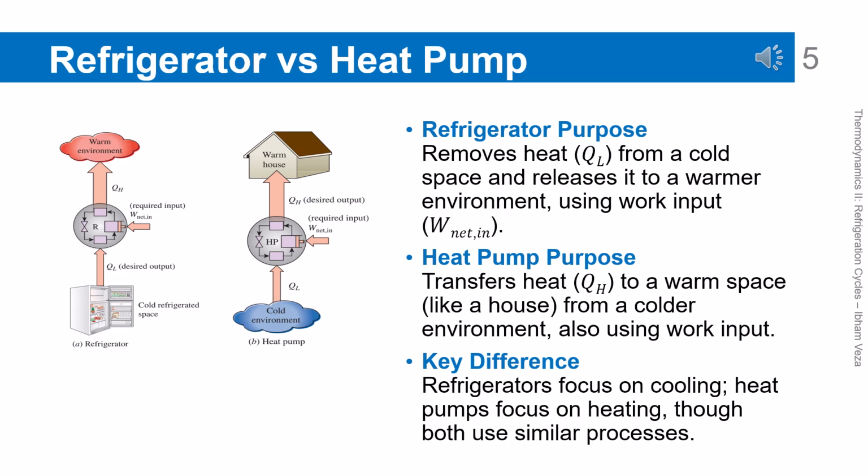Refrigerator versus heat pump. A refrigerator is defined as a device that removes heat, QL, from a low-temperature space and rejects it to a warmer environment. A heat pump uses the same principle but focuses on the heat, QH, delivered to the warm space. Both require work input, WN, to operate. From an energy perspective, the systems are identical. The only difference is the definition of the desired effect.